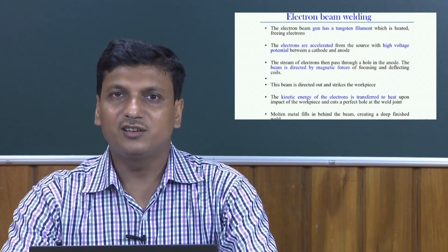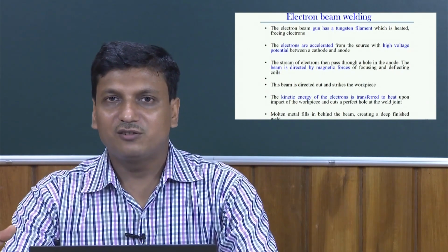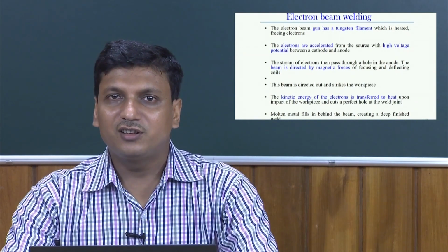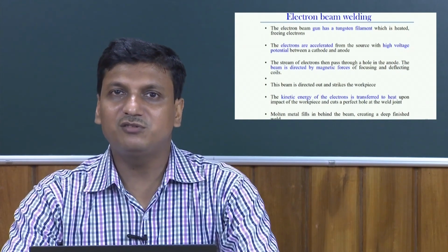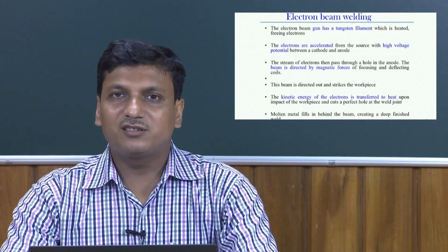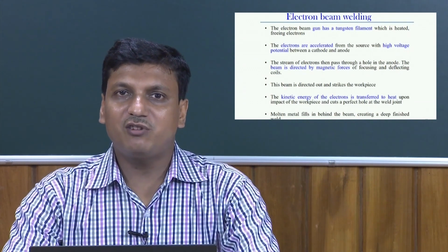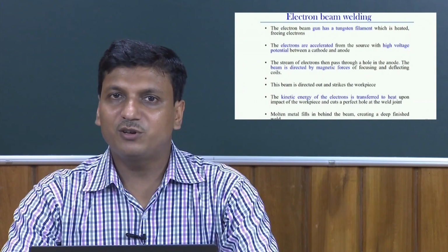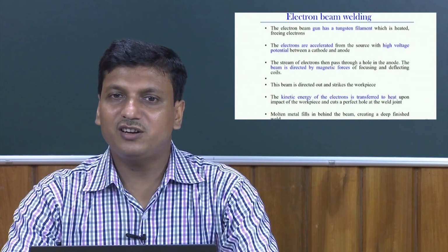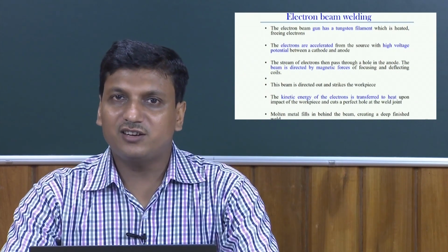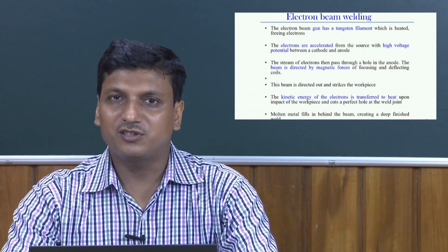But in laser welding, we can also create the keyhole mode, or deep penetration welding processes, even using the laser. But the point is that laser welding is not required to create any kind of vacuum chamber, and another point is that laser welding does not create any extra X-ray production during the process.